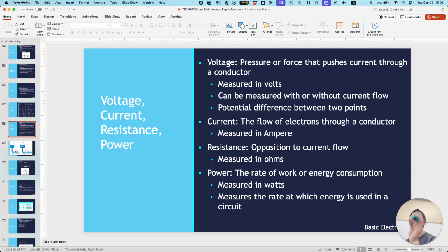So if you look at the batteries, if you guys still have it, you'll notice it says 14.8 volts. All right, so that's your voltage. We didn't read 14.8 because a battery is going to start at a level and then drop over time, just like a dam would, right? The water level drops to a certain point where even though there's still some voltage, it may not be enough to be useful anymore. Now the C rating on here, it says 100 C.